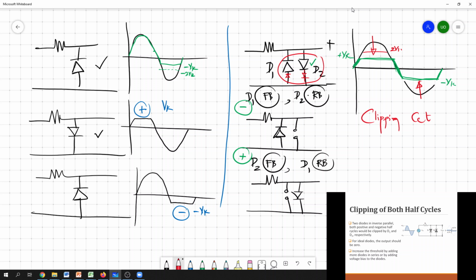So if you want to analyze a circuit, first you should stick to either the ideal model or the simplified model, which are the very commonly used models. Then depending on these models, initially you have to identify the actual voltage appearing across this diode by making the diode open circuit, or removing the diode, and evaluating the open circuit voltage across these two terminals. This is the open circuit voltage, and it's the actual voltage appearing across the diode.